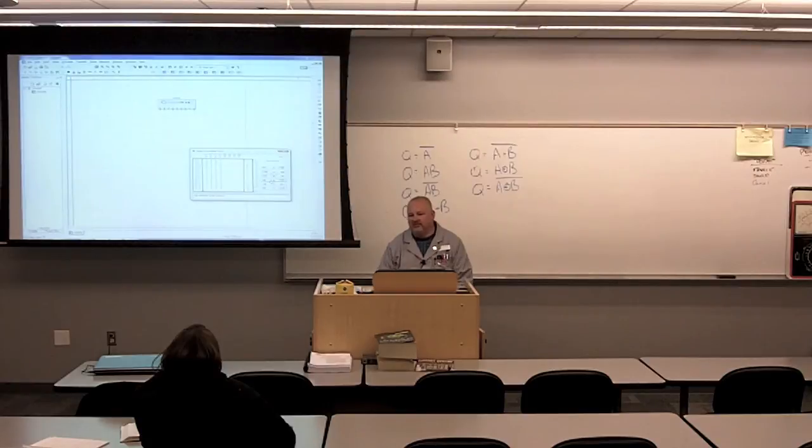Once I have the truth table, I could go from the truth table now to the simplified Boolean expression. This is really what you're doing in Karnaugh mapping, right? You're trying to go from a complex Boolean expression and simplify it. Once I have that truth table, I can click on this tab and it's going to simplify the Boolean expression for me. Okay, you ready? 3, 2, 1, click. There's the simplified Boolean expression: A naught and B and D, or B and C naught, or A and B naught. That's your answer.